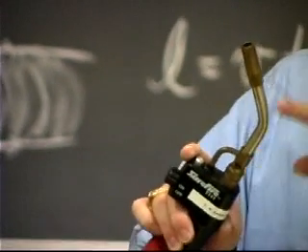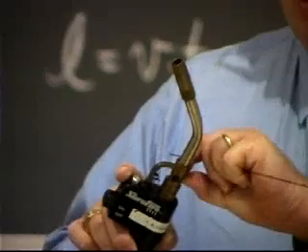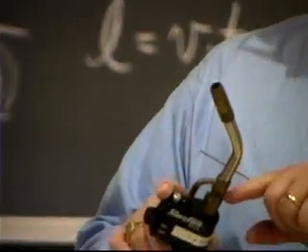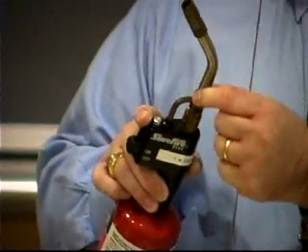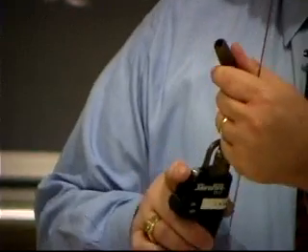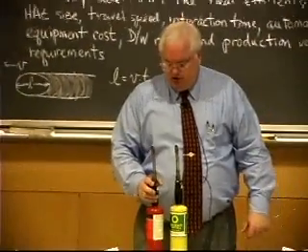And a jet of gas flowing at a high speed like this actually creates a suction, a vacuum by Bernoulli, right? It's called a venturi. And that sucks in the air through these big holes. And in here, I pre-mix everything. So this is what's called a pre-mixed flame. We'll go over those in a second. And then it comes out the end and burns out in the air. So this is a pre-mixed flame.